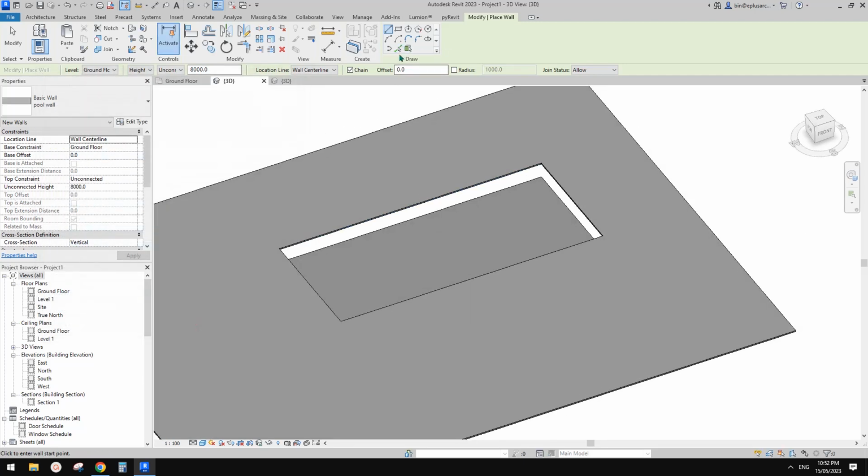And then usually I just do pick and just set here. Set from the floor. So for example, the base will be -1.8. Top will be the ground floor level, but sometimes you can still attach to the top, but I'll just leave it as 0.